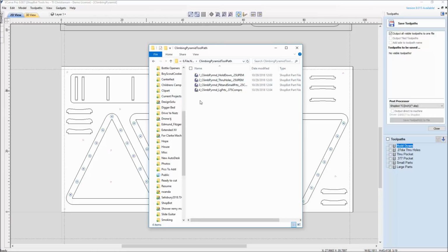And a couple things to keep in mind when you get into doing this. You have to stay away from special characters. And when I say special characters, I'm not talking about Buddy. I'm talking about using things like the @ symbol and backslashes, pluses. If you need to use any kind of characters besides numbers and letters, you can use a period or an underscore. Stay away from even spaces. Some Windows computers get a little bit grumpy, especially when you get into using the special characters.